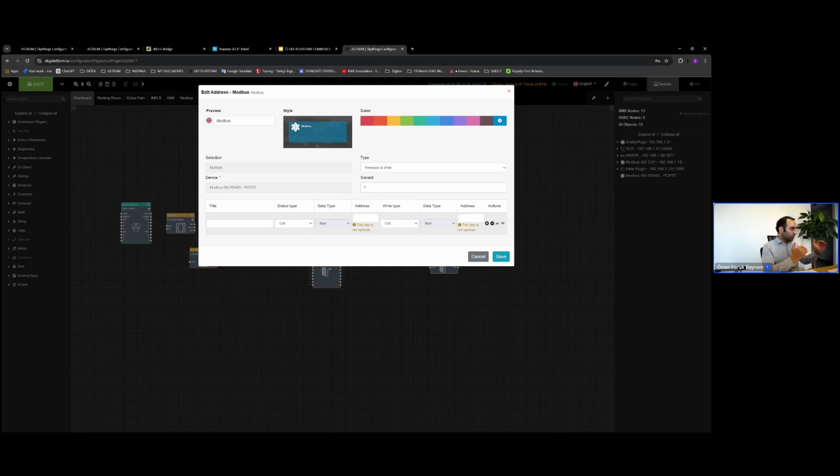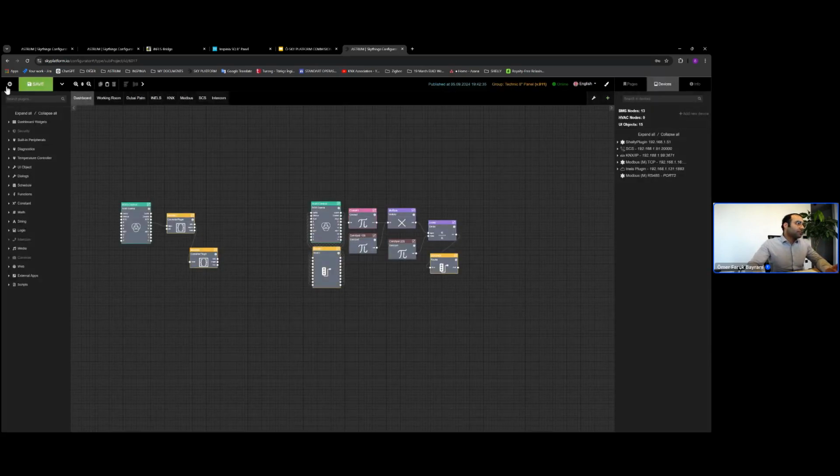After that, we will check the register table. For RS-485, for example, you will see the baud rate and the master or slave and the slave address, if it's slave. After that, these are connection settings. After that, you need to know addresses. You will add your addresses.